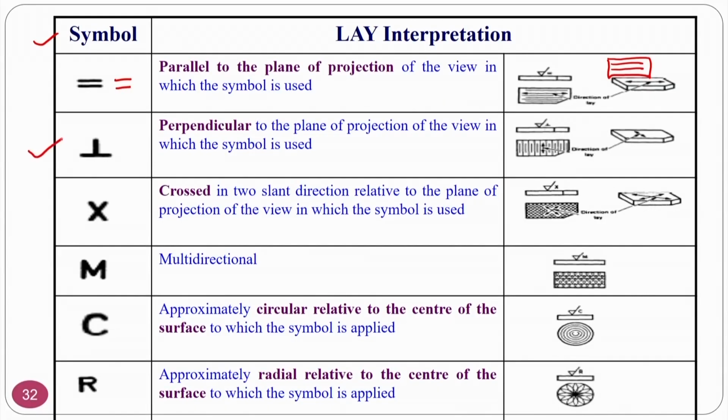Okay. Assume that you are rotating the grinding wheel in one direction, and if you place your workpiece in a perpendicular direction, and if your measurement is in the perpendicular direction, then it will be a perpendicular type of surface roughness.